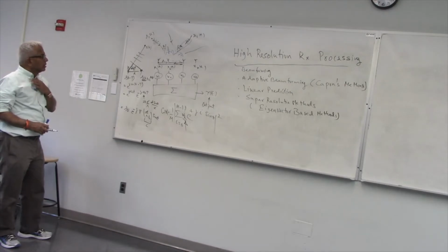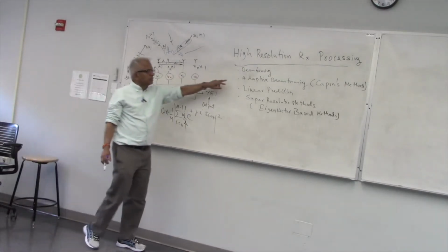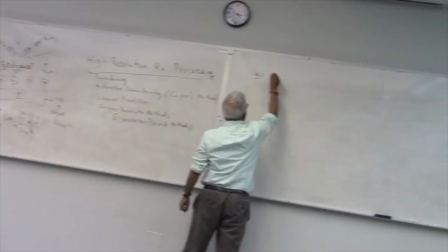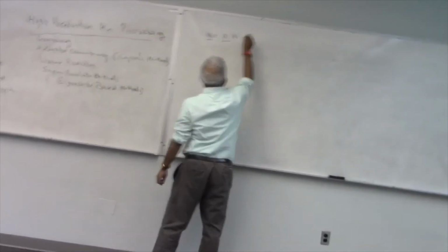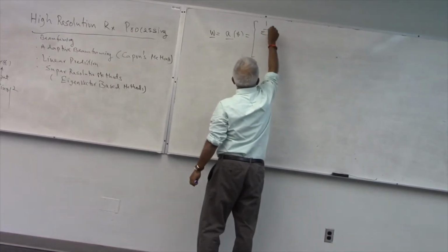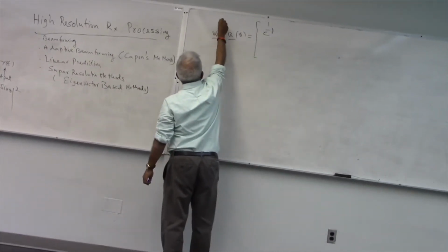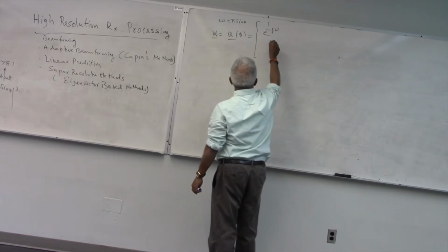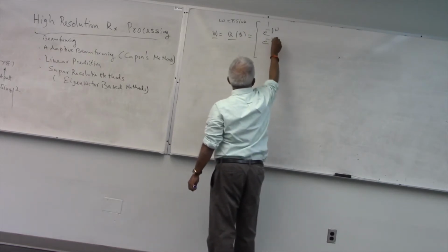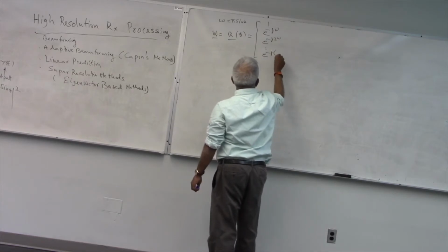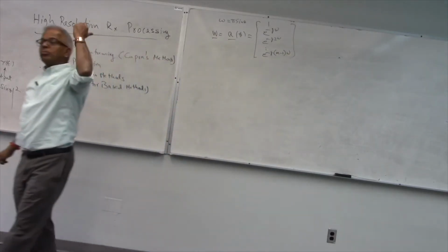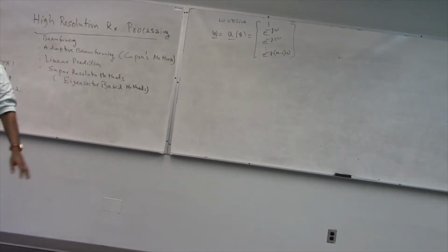Now, another way you could approach this problem here, so in terms of beamforming, we looked at the weight vector was simply a of theta. Remember, a of theta is the, so if I define omega to be pi sine theta for easy notation, then this becomes e raised to minus j omega, e raised to minus j2 omega, etc., e raised to minus j (m minus 1) omega. This is called a steering vector. The norm of this vector is square root of m, so if you divide by square root of m, you get a normalized steering vector if you want.